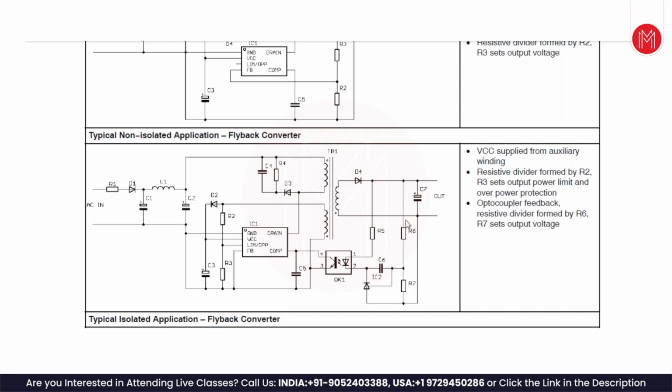That ratio of 2K and 1K together comes to 9 volts. That's how you use this ratio to obtain the voltage based on the reference voltage. This is always trying to put this voltage to the reference voltage, whatever it is. So the R6 by R7 ratio is used that way.